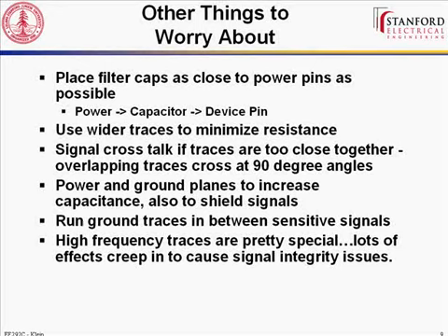But then to use both of those things, the power and the ground signals start bouncing. So the question is, if you use both the power and the ground plane, you have some bouncing. Well, we're assuming your current's not really flowing off your board and back to an alternate ground. We're assuming you don't have a ground loop somewhere. So they'll be bouncing together, so your common mode is going to be pretty low. And the other thing is that just because you have a very large area of ground, or a very large area of a conductor even, you basically get Faraday shielding. So there can be some emitted noise, especially from power planes if you have a lot of different power planes, but ground planes do a very good job of shielding.